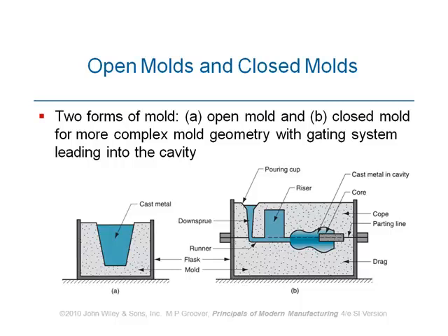So, as a consequence, we've got to take into consideration that when we are making the cavity, we've got to make it slightly larger in order to compensate for the shrinkage. Right? By how much? It depends on the type of the material, specific heat energy and the properties of the material. And there is a table in the textbook telling you how much bigger you've got to make the cavity, which depends on the type of the material. Often, we've got to make the cavity between 1 to 3% larger.